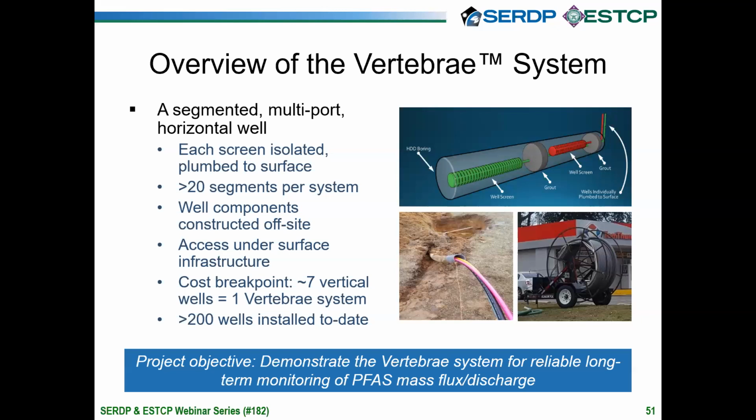If you're going deeper, you need to step back further to get to depth. Now with these smaller systems, I think the angle can be a little bit more aggressive, but the depth is more controlled by the length. So I will say, I've got personal experience installing horizontal wells to maybe about 130, 140 feet. And for most unconsolidated systems, we don't need to go deeper than that.